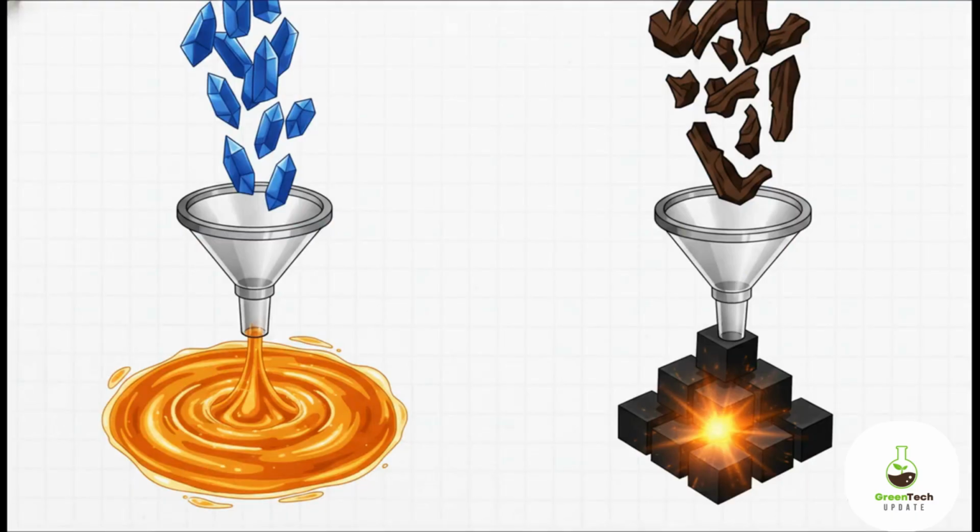Because of all this, your feedstock selection strictly dictates your output. High cellulose feeds are going to maximize your liquid bio-oil yields, pushing nearly 67.5% at 500 degrees. But high lignin feeds will optimize solid biochar production. And crucially, that lignin-derived biochar has the highest heating value, or HHV, thanks to its incredibly dense, carbon-rich aromatic structure.